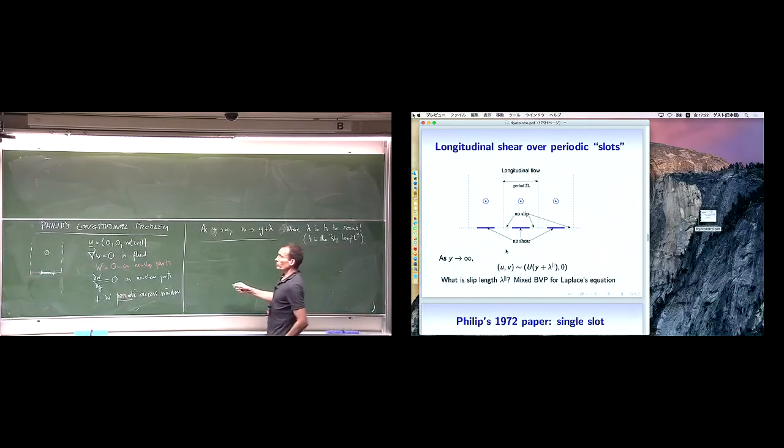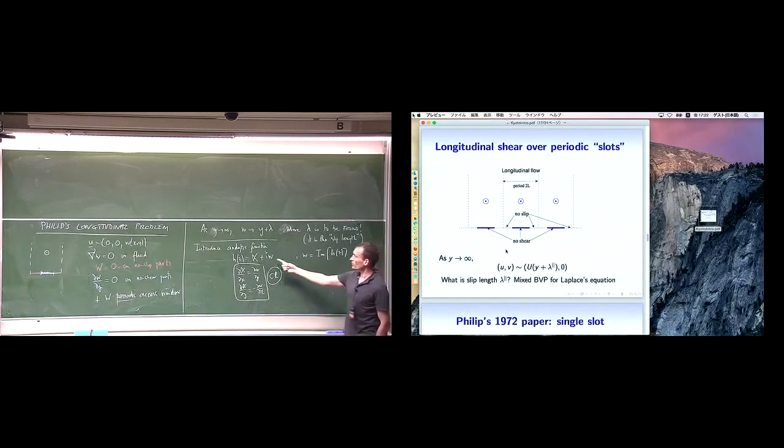Okay, let's introduce complex potential. Introduce this h function, which is chi plus iW. So in other words, W is the imaginary part of some h. And we all know, by the way, that d chi by dx is dW by dy, and d chi by dy is minus dW by dx. These are Cauchy-Riemann. Remember? That's what I mean by the harmonic conjugate. So W is what we want, it satisfies this. Chi is its harmonic conjugate, the function that satisfies these Cauchy-Riemann equations.